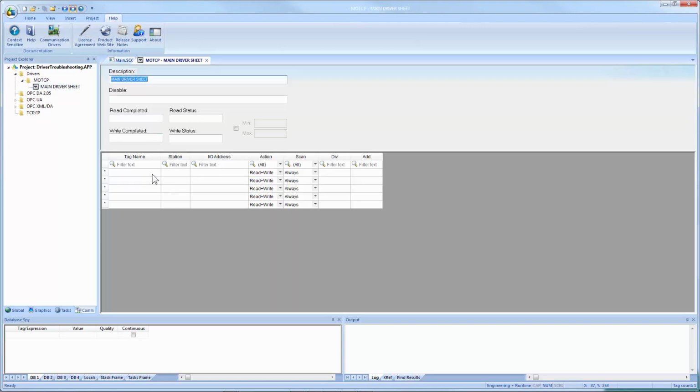And again, this is a 600 millisecond scan rate, and you don't get a lot of flexibility to modify that. There are some ways to do that, but you really get these 4 status fields, and a lot of applications that I get to take a look at have no tags in these fields, and that means that they're not monitoring whether or not they have communications.